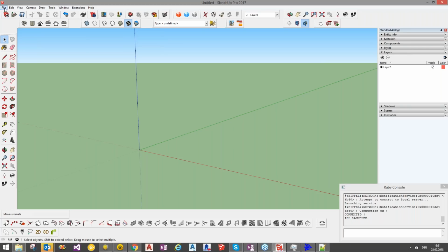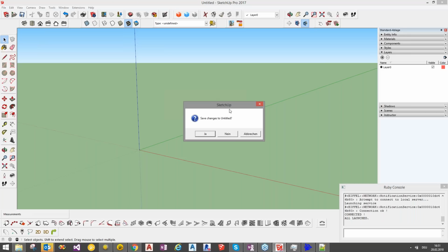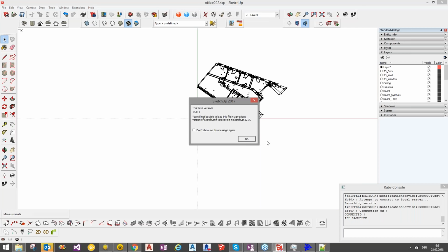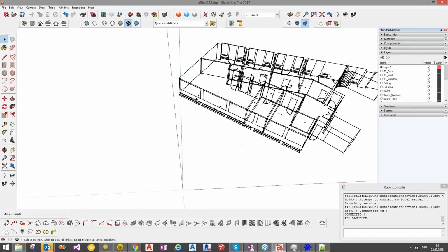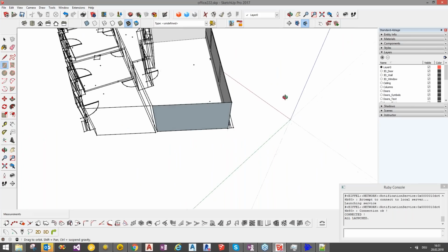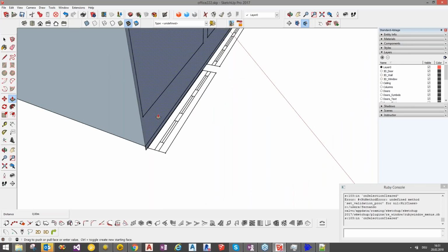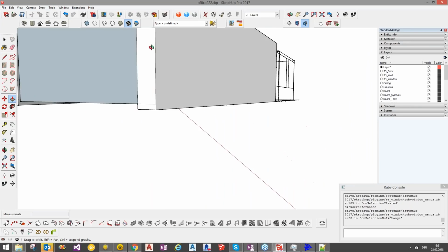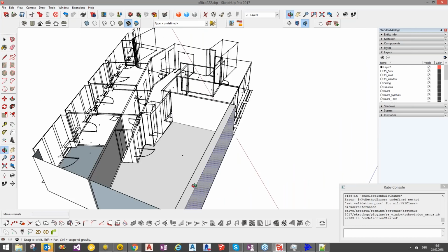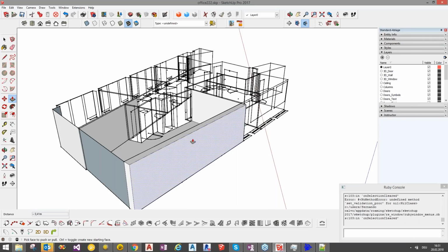The same would happen inside SketchUp. So we can open SketchUp, the SketchUp file that we just created from TBC. So we go to the file there. This is the Office 222. So we have the 3D representation, and if you need a bit more 3D definition, you could simply create your walls this way, and pretty easy finish your drawing, creating the parallel walls, etc. So you could use the reference lines for the widths, etc. You could import and insert your doors, windows, etc.